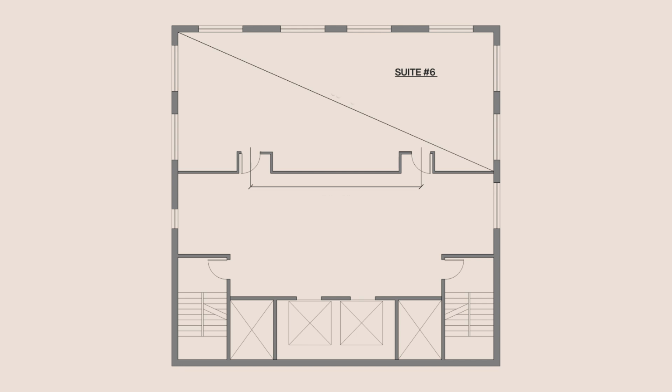Having an automatic fire sprinkler system allows people more time to reach an exit because you have water that's mitigating the fire. So you have a little bit more wiggle room in terms of the time that you have to safely evacuate a building. If we look at the example shown, the total diagonal distance of suite number 6 is 63 feet. If this were an unsprinklered building, that means that our 2 exits must be at least 1/2 of 63 feet, or 31 feet 6 inches, apart from each other.